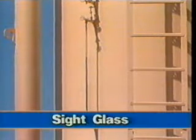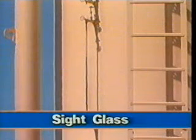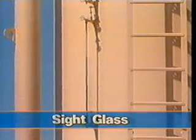Sight glasses are the best way for the pumper to see if the treater is doing its job. Should the sight glass break and stick wide open, a safety feature within the gauge will cause a steel ball to seat, shutting off the flow.